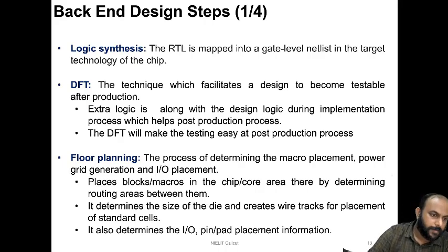Okay, so after DFT insertion is done, typically the next step is floor planning. Floor planning is an iterative process which basically does a few things. It determines the macro placement, the power grid generation, and IO placement. Macro placement means the logical placement of where things should be placed on your die.